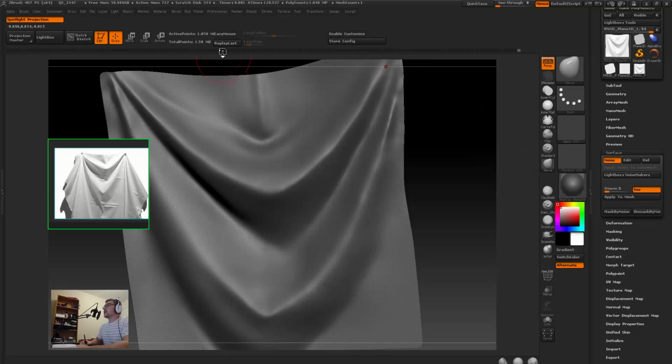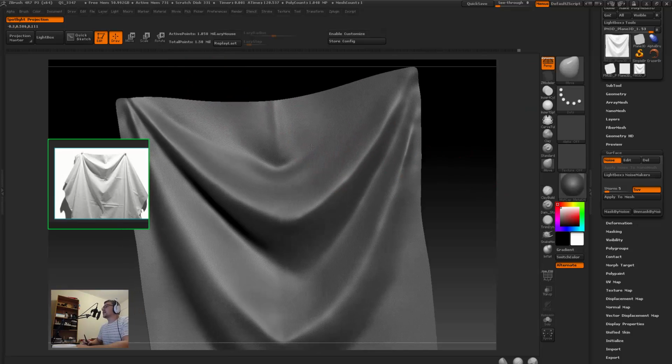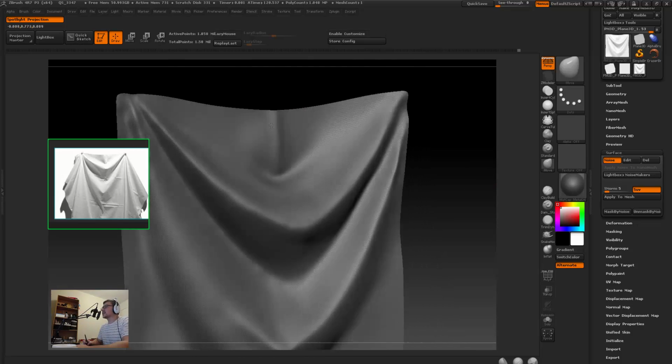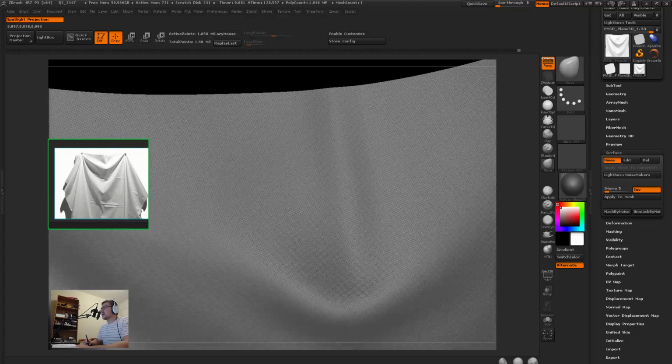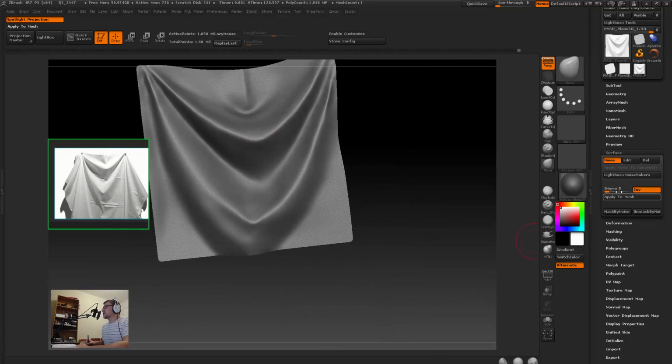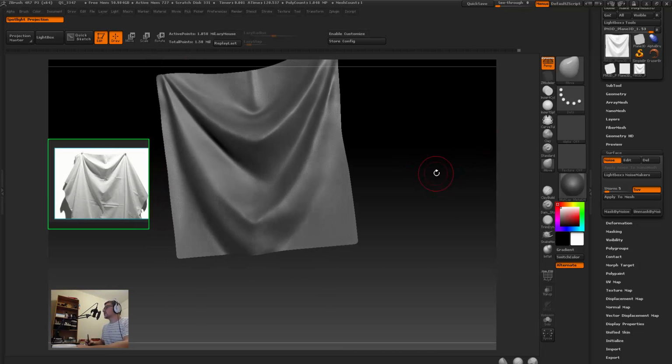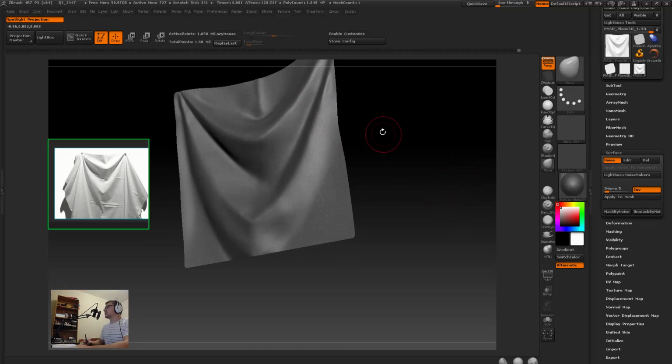One thing that you do need to keep in mind is that the result of the cloth texture being applied to the mesh is limited to the amount of polygons we have in the scene. So if you have very few polygons, you won't be able to capture these details. Currently the surface noise effect is previewing more like a bump texture. So it's not physically applied yet. It doesn't have any depth to it. So if we have only a small amount of polygons, it won't be able to capture those details. So just keep that in mind whenever you're working through these workflows.